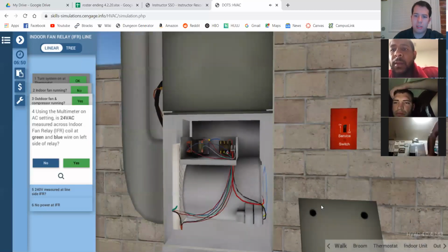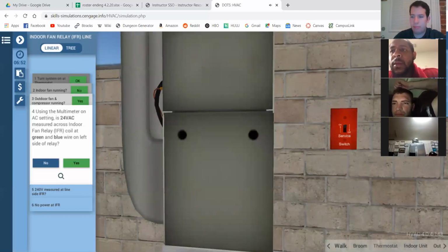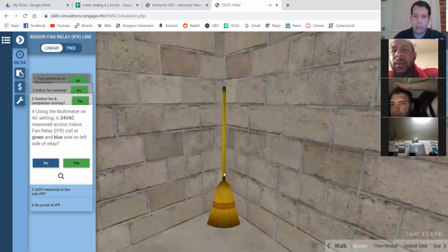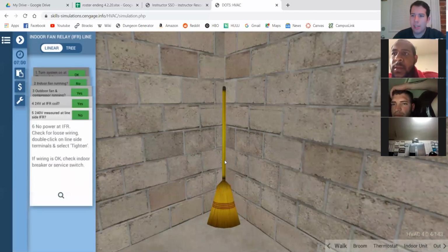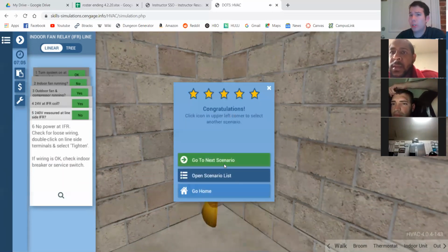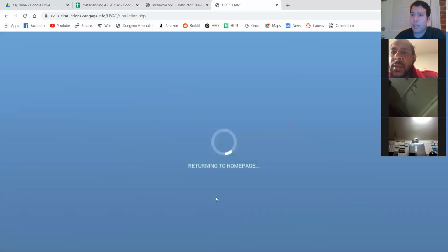And again, this is the kind of stuff that gets overlooked, and I know I do the same thing. It's like, there's no way it can be something that easy, it's got to be something complicated. It's air conditioning. But a lot of times it ends up being just loose connections, poor connections, damaged wires. Stuff like that is very, very common to come across.